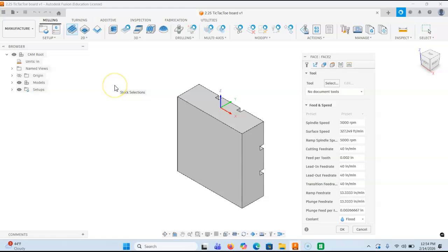When we go to set up for a facing operation, the facing toolpath can be created by selecting the whole face itself. As you take a look at this, we can select that whole face, or we could select this face, depending on which side of the part we're working on. Once we've got that selected, we would define the tool, geometry, heights, and passes. In that selection, it is typical to select the largest cutter that you have.